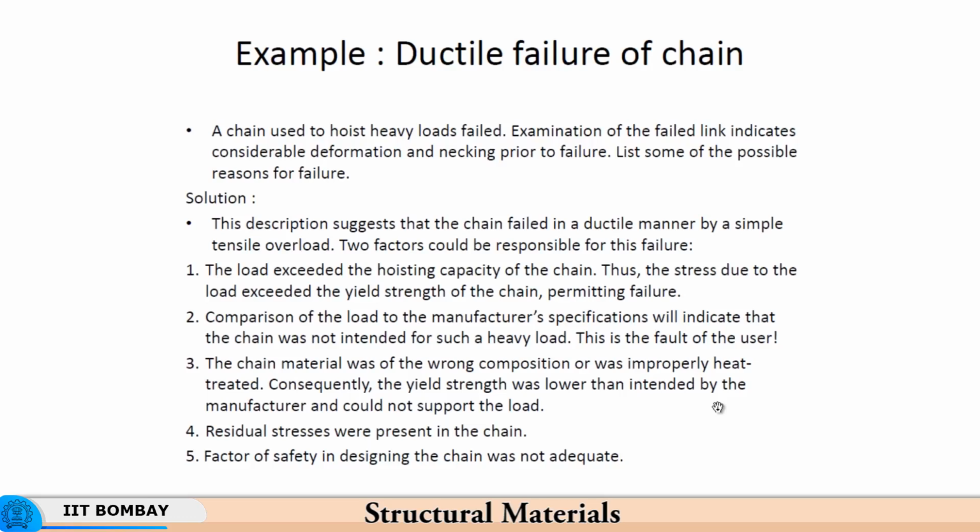So, as I was explaining to you about the rope, because of overload, the cross sectional area continues to diminish because of plastic deformation, permanent deformation, and then the permanent deformation went to the extent that the failure took place by necking, meaning localized plastic deformation prior to failure.